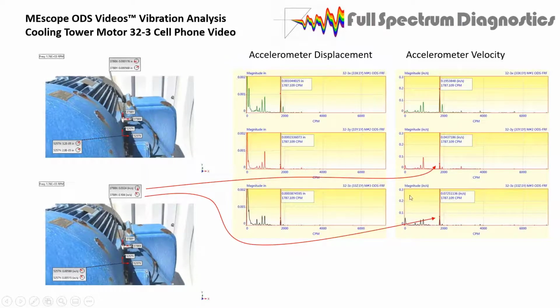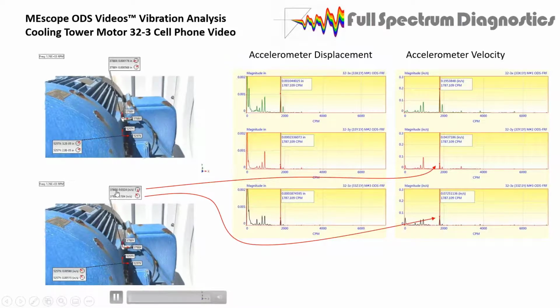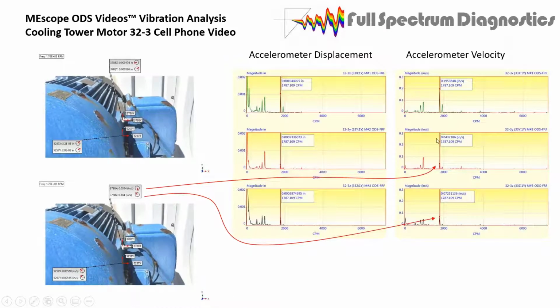If I integrate that or differentiate the displacement to velocity at the same speed, I'm now getting a good severity factor. So whatever this is, all I have to remember is if it goes above 0.3 inches per second, then there's some issue developing. Okay, so here's a 0.03 inches per second and 0.1 inches per second. This was in the X and Y direction on the interface between the magnet and the bearing housing. So over here, I got 0.043 and 0.072.